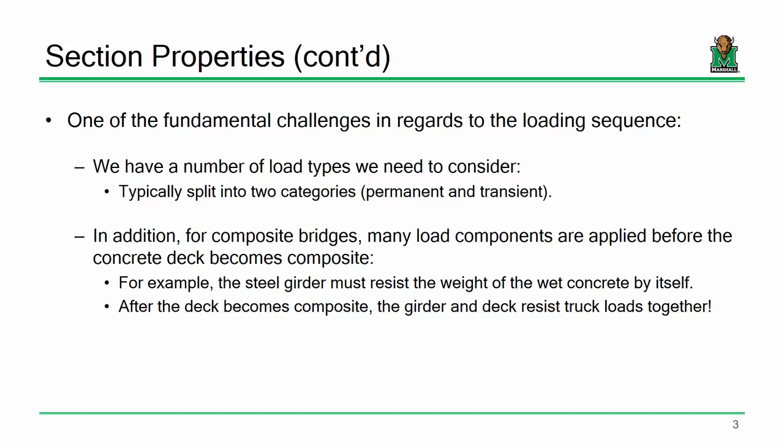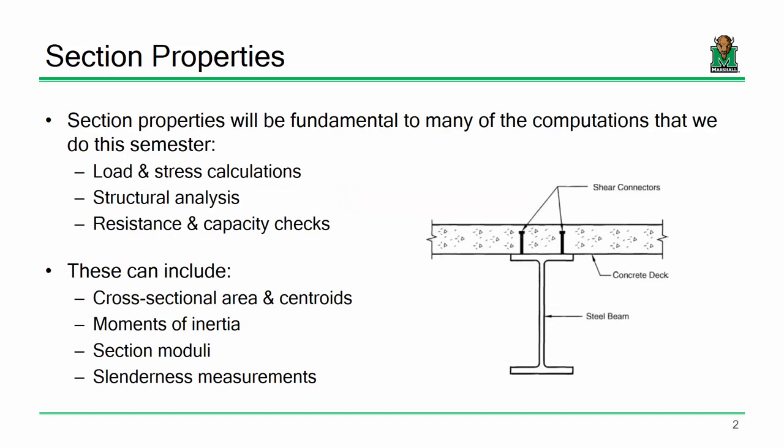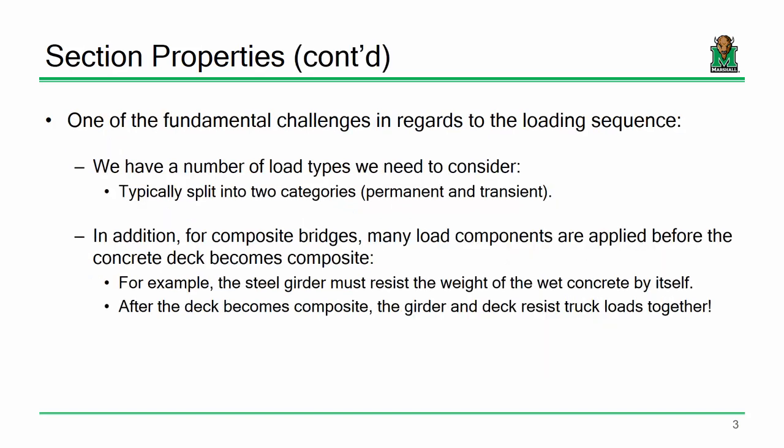Okay? What makes bridges unique, and specifically the case when you're dealing with a composite structure, something like this, is that concept of staged construction. So I want you to mentally picture what's going on during a typical bridge construction. So let's say I'm trying to cross a bridge from here to here. Okay, so I've done all my earthwork, done all my grade work and what have you, and I've driven piles or whatever, and capped my abutments, and I'm ready to place my girders. So what happens?